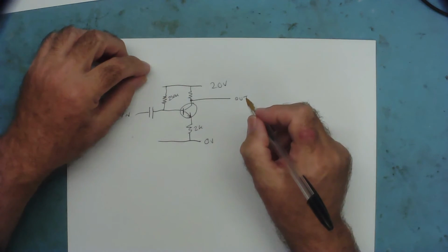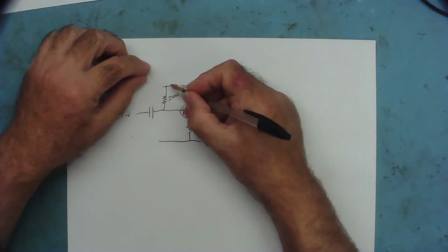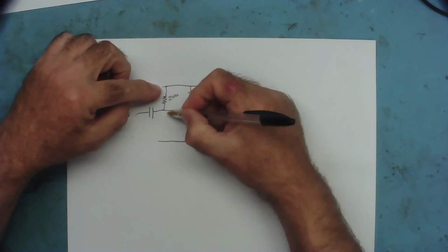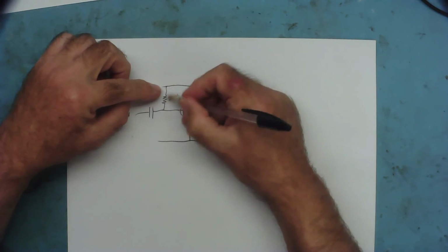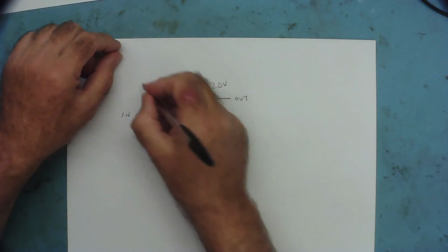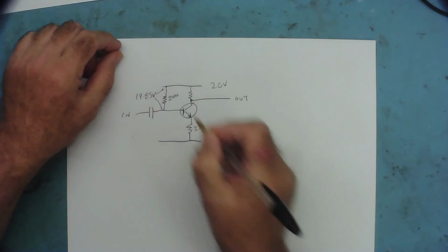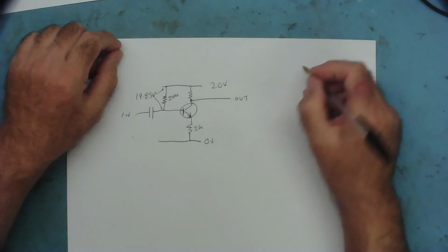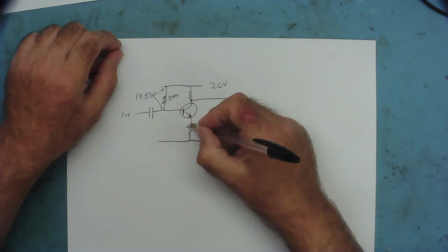And we measure the voltages again. So we measure the voltage first across this resistor, yeah. Let's measure the voltage from here to here, yeah. And what have we got? We get 19.85 volts from there to there, yeah. Now let's measure the voltage from the emitter to ground, the voltage across this resistor, yeah.